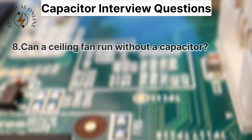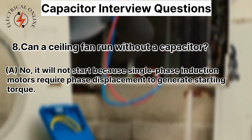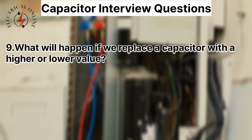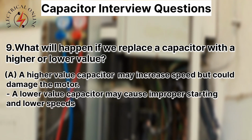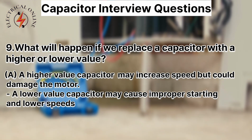8. Can a ceiling fan run without a capacitor? No, it will not start because single-phase induction motors require phase displacement to generate starting torque. 9. What will happen if we replace a capacitor with a higher or lower value? A higher value capacitor may increase speed but could damage the motor. A lower value capacitor may cause improper starting and lower speeds.